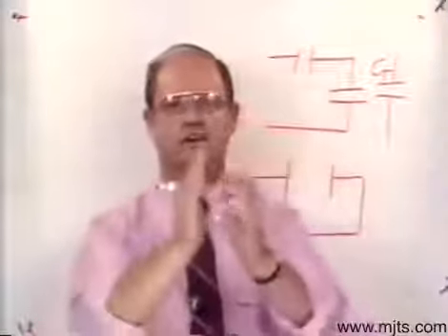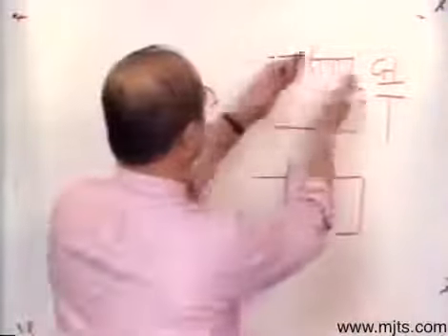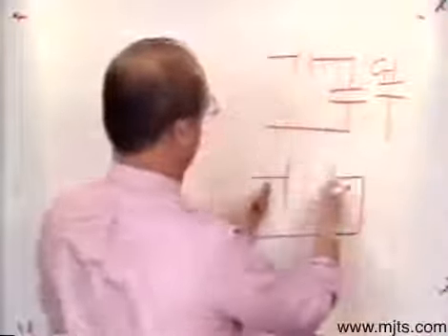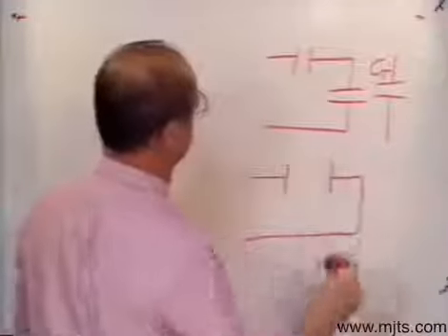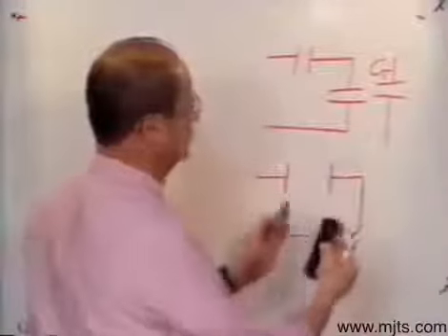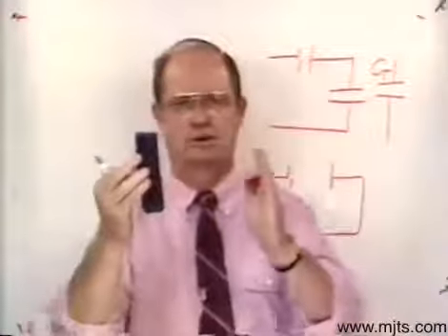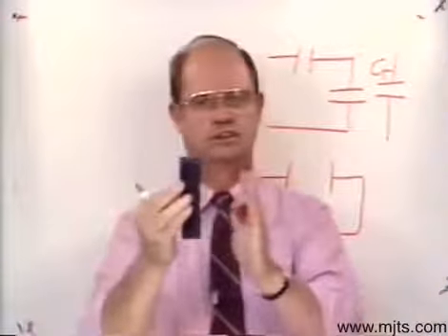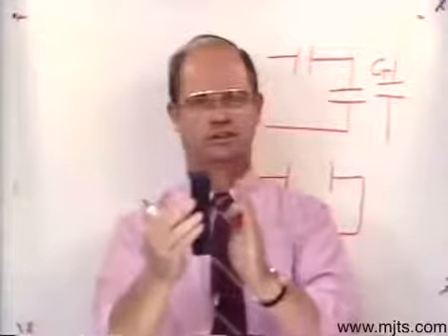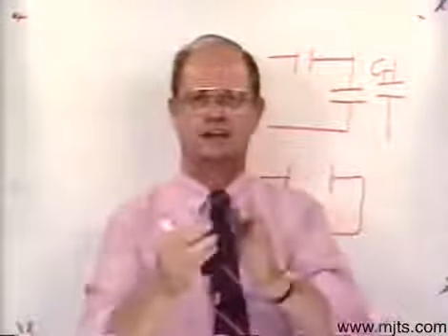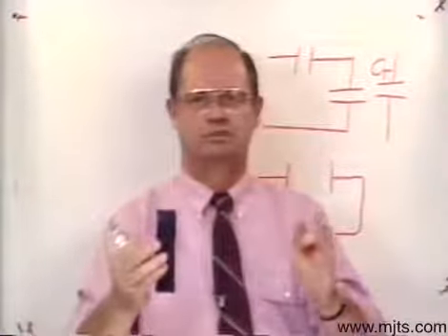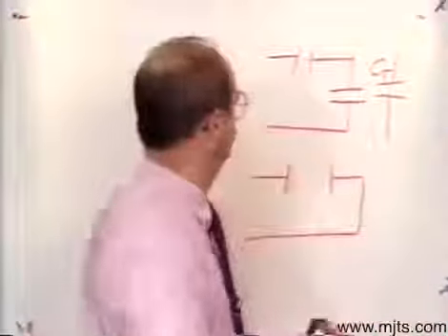And it's because it's like a plate of the same size, only twice the distance between it, like I've shown you right here. See? So I'm going to have less capacitive effect. Remember, we talked about the distance between the plates determining the value of the capacitor. This series has an effect of adding a greater distance between my plates. So I'm going to have less capacitive effect.